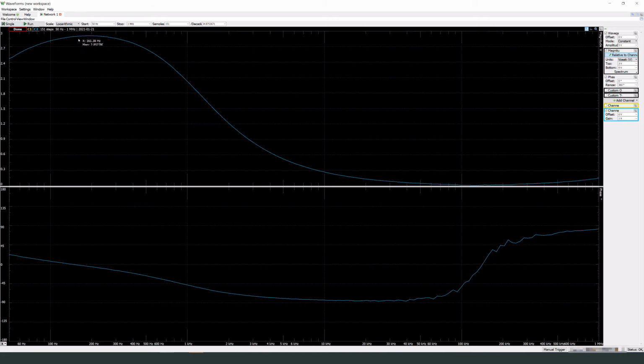So what we have here is the frequency response. You'll see as we go to the frequency of 250, which is one of the ones we're interested in, we get pretty much near the top of this curve, and so that's nice. We'll get most of that output. And then if you go over to 500 hertz, you'll see that we're over here, which is still pretty high up there, and this is where the output was for that frequency. And so the 500 hertz will be slightly attenuated compared to the 250 hertz.